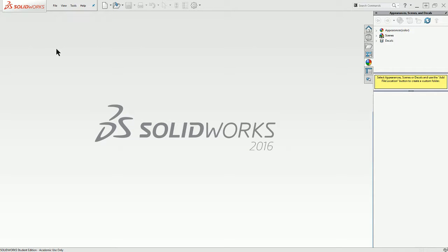So we're going to make an assembly, and in SOLIDWORKS an assembly is really nothing more than an association where SOLIDWORKS builds a second file called an assembly file that associates all of your part files in a geometric configuration. So that's an important thing to remember. The first thing to think about is that the association of the files is important. So once you build your assembly, you have to be very careful to not alter that file structure or your assembly will break. So we'll talk a little bit more on that, how we'll submit our files so that we don't break that association.